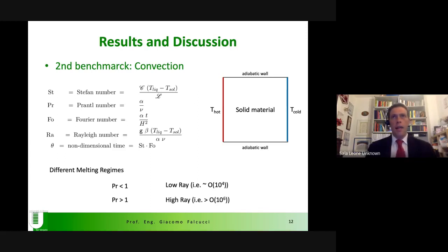For higher Prandtl numbers, that is more than 1, it is known in literature that for large enough values, from about 3.5 and more, the effect of the Prandtl number becomes almost negligible. So there is not a great difference in running a simulation with Prandtl 10 or 50, okay? And this field is the one that characterizes the behavior of paraffins and organic molecules, which are of greatest interest for us engineers for thermal energy storage.